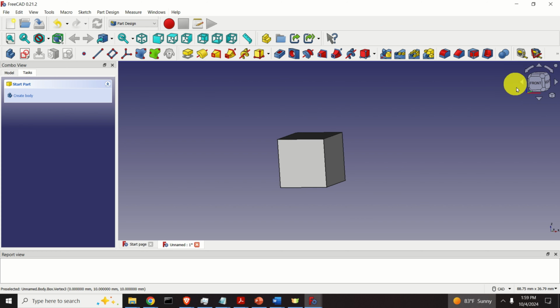If you cannot find this icon over here, you can simply click on Part Design, and over here you have several options. If you click on Create on Additive Feature, you can click on Pad and you will be able to extrude. Simple as that. Good. Here's our 3D object. Let's rotate it. Looks good. The next step is to define circles that are used to define holes.